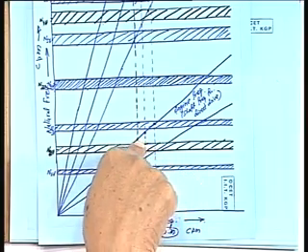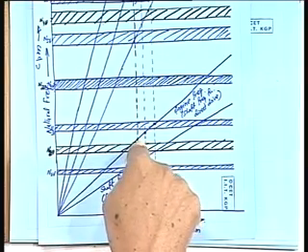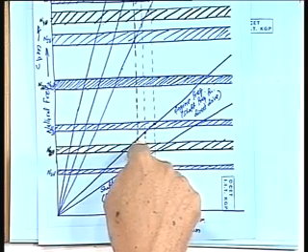Okay. So, if you try to cut down the MCR, what I am trying to say is that all this RPM and the engine RPM we are talking about is whatever is the operating RPM. If you are designing a vessel to operate at 80% MCR or 85% MCR, then this is the 85% MCR RPM. If you say it is 100% MCR, it is 100%.